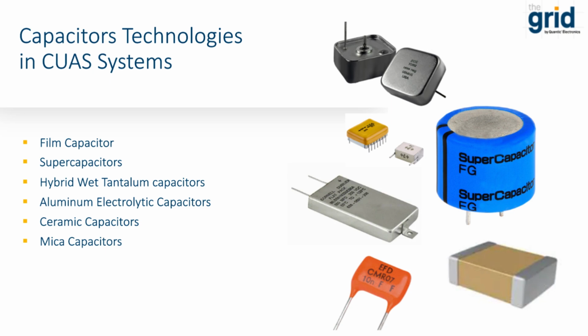Hybrid rectangular capacitors are somewhat similar to supercapacitors. They are known for their high energy density, but with an increased voltage range of up to 125 volts in a single capacitor. These are ideal for power holdup applications of power systems, TR modules of radars, and powering high power applications such as pulse lasers and electromagnetic pulse.